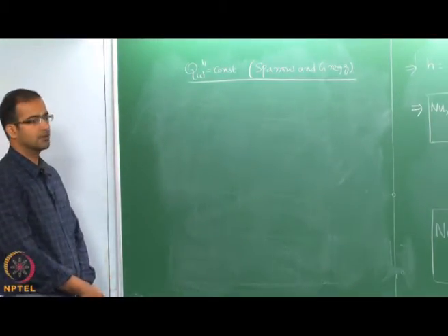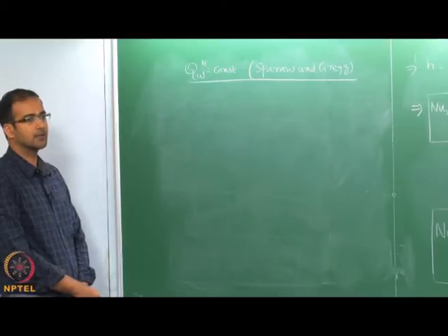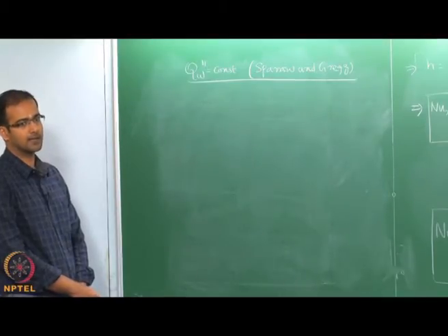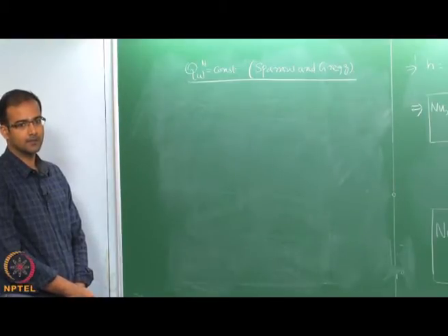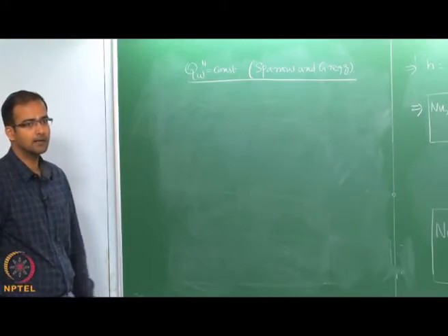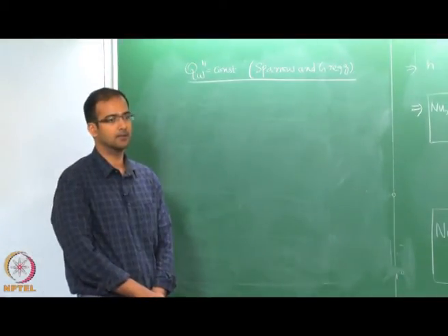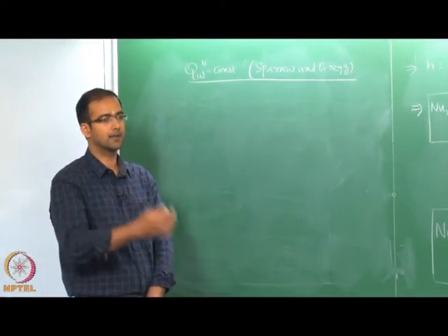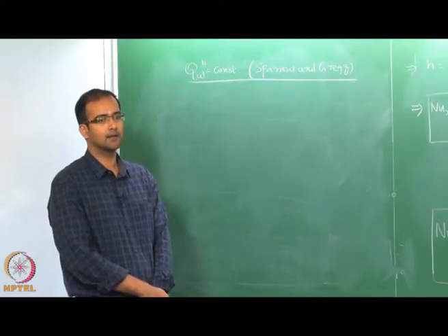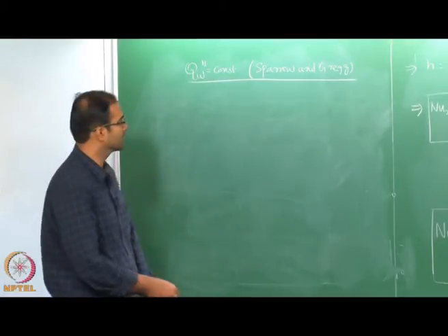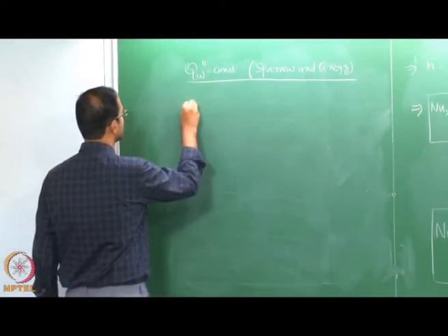Okay. So, now similar to the flat plate case where we had constant heat flux boundary condition, we have to find another similarity variable. We use more or less the same similarity variable there, but the way we have defined our non-dimensional temperature theta differs.